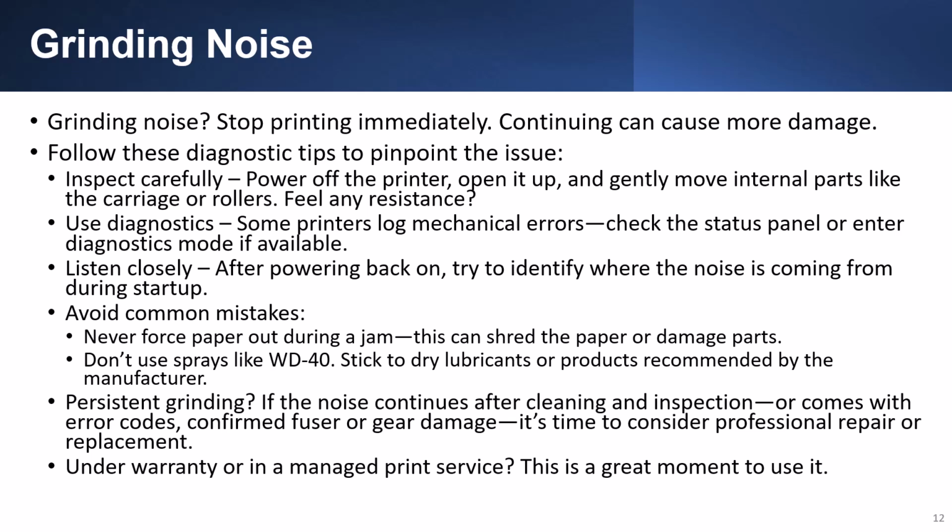When you hear a grinding noise, stop printing immediately. Continuing can cause more damage. Follow the diagnostic tips to pinpoint the problem. Inspect carefully. Power off the printer, open it up, and gently move internal parts like the carriage or rollers. Feel for any resistance. Use diagnostics. Some printers log mechanical errors. Check the status panel or enter diagnostic mode if available. Listen closely. After powering it back on, try to identify where the noise is coming from during startup.